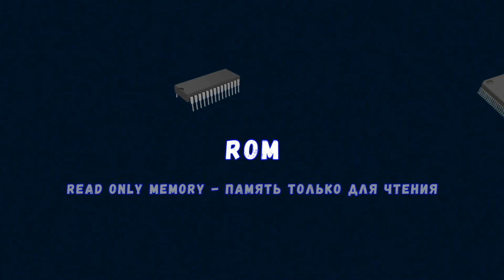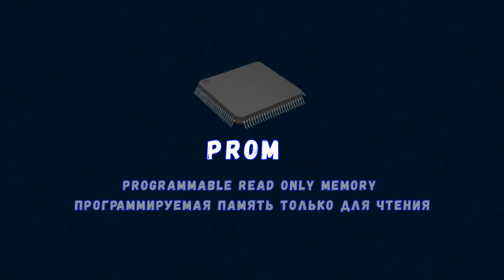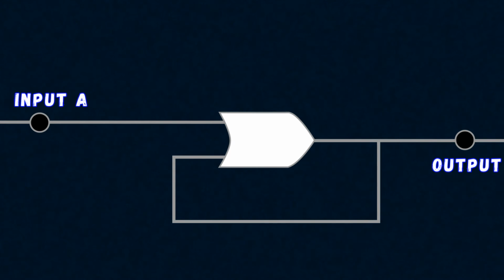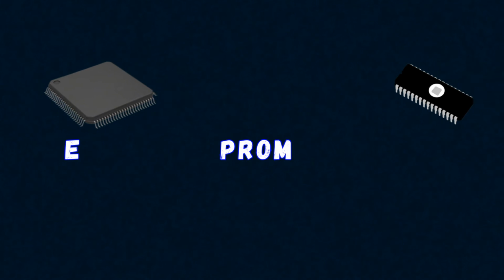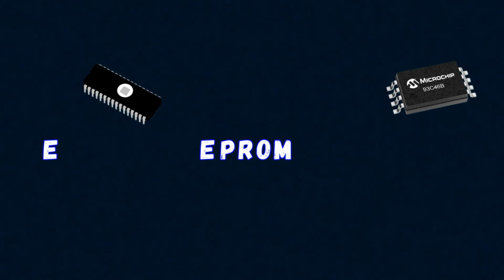First, the so-called PROM, programmable read-only memory, was created, which could be programmed but only once, like being able to write data only once to our simplest memory cell made of one OR gate, as we started the story. Then EPROM, erasable programmable read-only memory, was created, which could even be erased and rewritten, but through various clever methods, such as exposing the microchip to ultraviolet light.